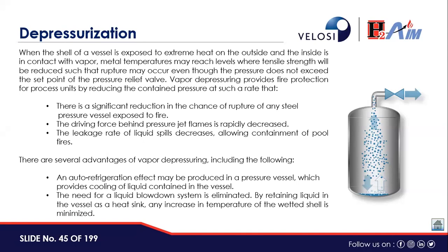It's also called emergency relief. API 520 and API 521 provide guidelines for the use and design of relief systems as required. There are various causes to initiate depressurization, but it is part of the emergency response or mitigation system.